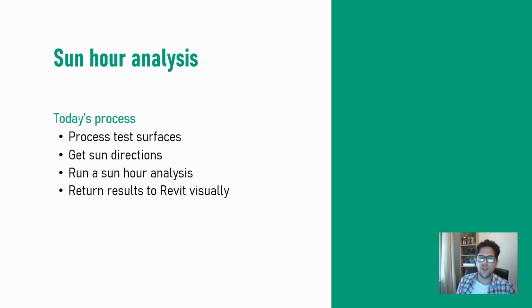We are going to use the sun direction in Revit. I'm not completely trusting of this data. I don't know if Autodesk keeps it up to date. Typically we use weather files that come from airports at very specific places in the world for proper solar analysis. So just be aware that sometimes the sun direction in Revit may not be the best reference.